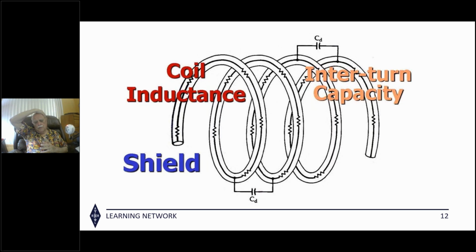Next, what is the best balun to use for a gutter antenna? The famous gutter antenna. I have one, by the way, except I didn't use my gutters. I find that rain gutters are tough to deal with directly, and you certainly don't want to lay the wire in the gutter if it's a metal rain gutter. Plastic ones you might. What I did is I made some little 1-foot standoffs out of PVC pipe to look like vent pipes, and I located 6 of them on the edges of my roof. So when the neighbors look up there, they don't see an antenna. They just see some vent pipes, and the wire that runs around is on top of those little vent pipes.